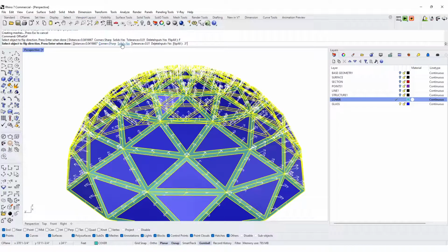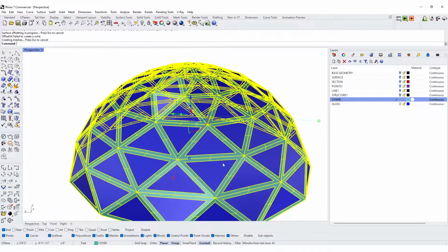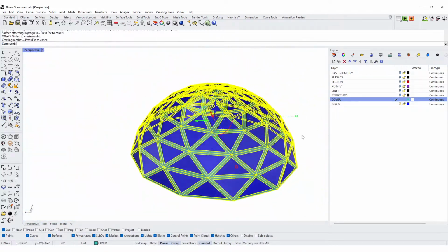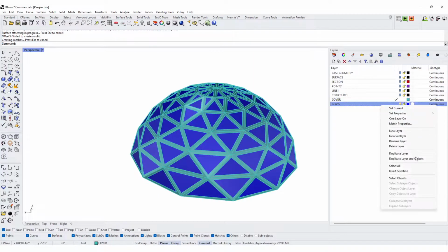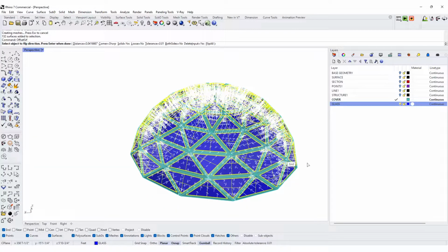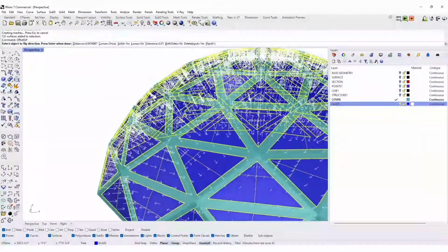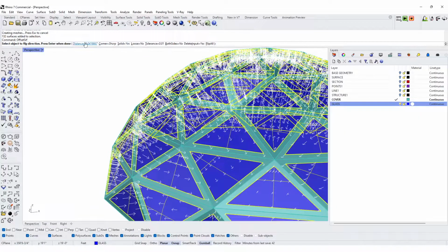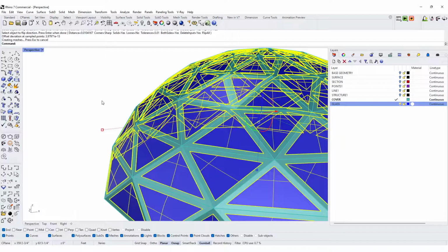Make sure that it says sharp, solid is fine. You can have it round and then open, but that won't give you what we need, so just make sure you have solid on, yes. And then we hit enter, it will calculate and do the offset for that. Now what we need to do is select the blue one, glass, select objects, and we'll do offset surface. Both sides, here where it says, yes. And then we'll do 0.125 inches, just to give it a little bit of thickness for the glass.